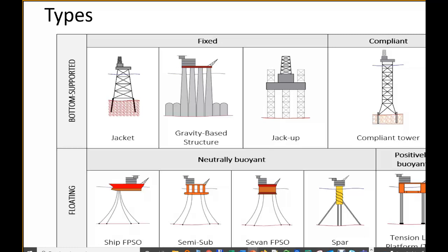And then you have this tension leg platform, which is the only one. All of them are floating by themselves freely, but with this one you attach some tendons, some tethers, to the seabed. These tethers are in tension, so they are pulling the structure, this TLP, down. If they were not in place, it would simply float up and be much higher. It would be unstable. So these tethers are in continuous tension, bringing it down, and that's why they call it positively buoyant.